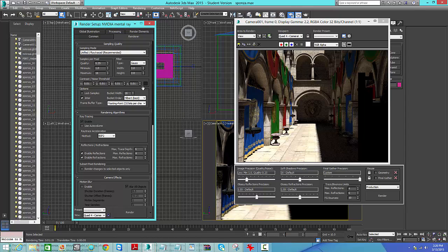What this does is it's basically setting the contrast threshold for sampling. So when it takes the anti-aliasing sampling, it's going to determine how deep it gets before it clamps that sample so that it doesn't go any further into the contrast. For example, in this shot, with the actual render here, if this was set higher, you would actually have clamped shadows that come out darker. But because it's 0.01, it gives you a nice variation going into the shadows.